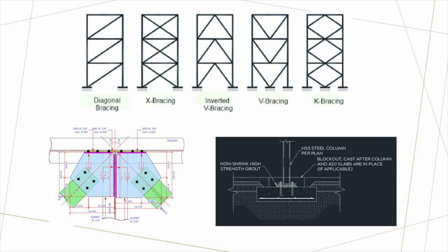Braced frames are designed to collect lateral loads and transfer them to the foundations. These braced frames are usually designed similarly to columns due to the fact that compression typically controls bracing size because of buckling. It is important to note that the connection at braced frames should be designed for tension to allow failure of the brace prior to the connection in the case of a seismic event.